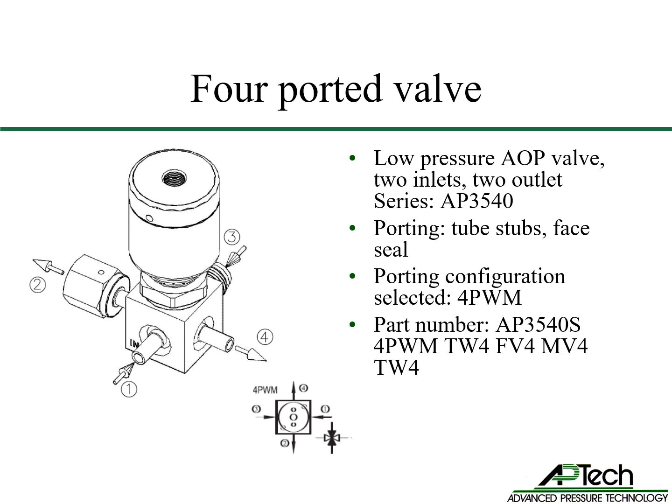Looking at APTech's product note number 443, a 4-ported valve with 2 inlet ports and 2 outlet ports opposite is a 4 PWM flow pattern. Again, when configuring the part number, the ports are specified in sequential order, starting with port number 1. So the part number is AP3540S 4 PWM TW4 FV4 MV4 TW4.